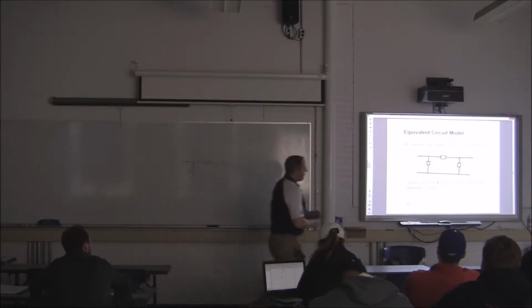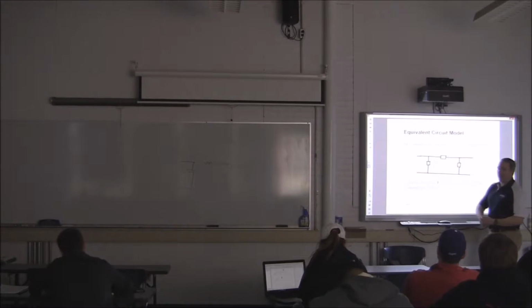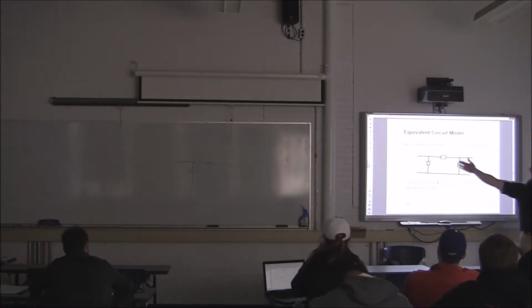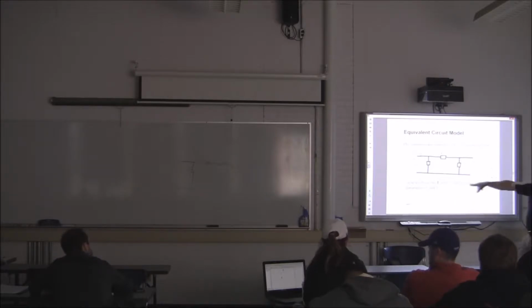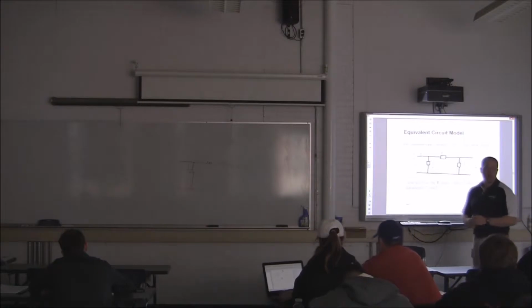What typically happens in industry is we take this capacitance value that we have over here, and we want to see its effect on both ends. We want to see what happens on the sending end as well as the receiving end. So we break it up and put it into two. And that will allow us to come up with our pi equivalent model.